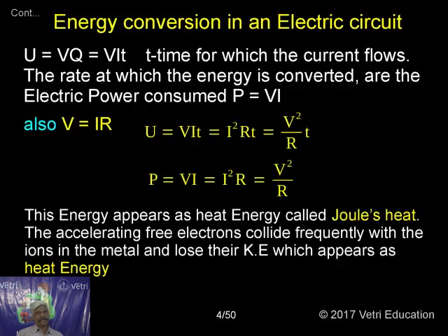Then what is power? Just like work done, what is the power? The work done in unit time. That means work divided by time will give power. Therefore, I should divide it by time. If the answer comes with T, that is called work done or energy. The rate of doing work is called power. Therefore, simply VI, I squared R or V squared by R.